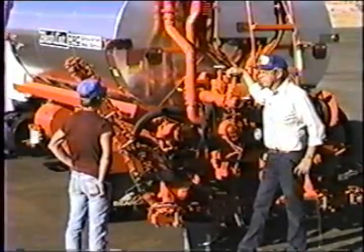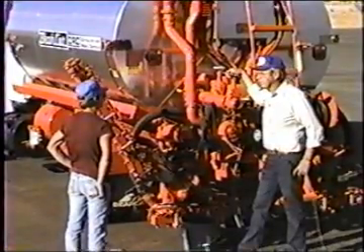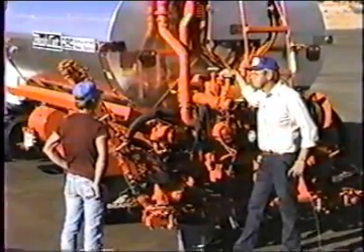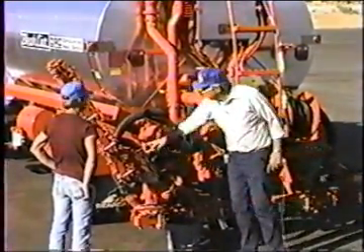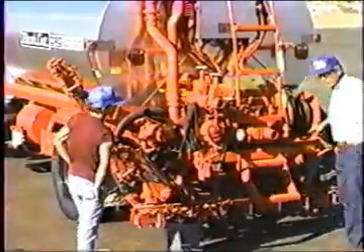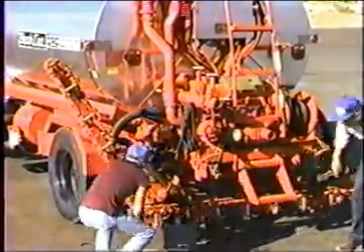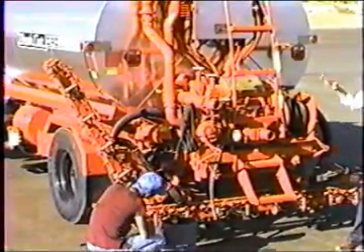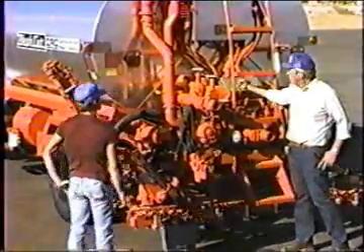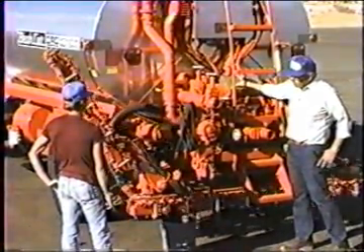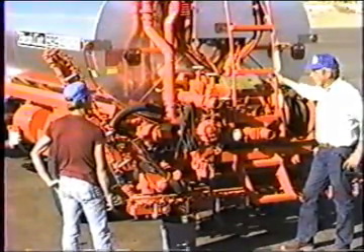Very simple valve. It's got a double ball check in there, and it's probably got a piece of rubber out of a hose in it, preventing the check valve from working. There's four of them, actually, there's 5 on this truck. There's 2, 1 for each of these wings, 2 on this side, 1 for each wing, and then the 5th one is down underneath, and it's on the spray bar itself, the raising and lowering of the spray bar. We want everything to stay exactly where we set it with the hydraulics. That is, if we set the spray bar at that height with the hydraulics, we want it to stay right there. And the lockout valve causes it to do that.